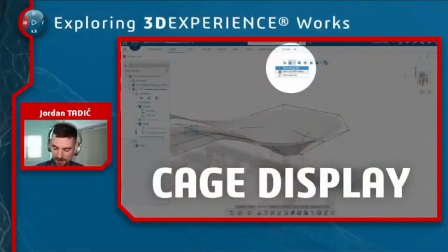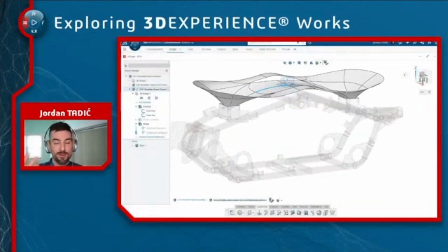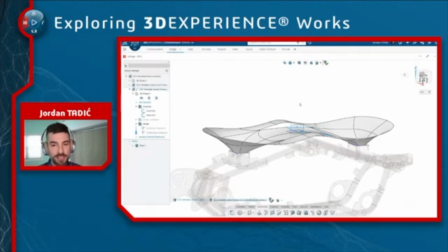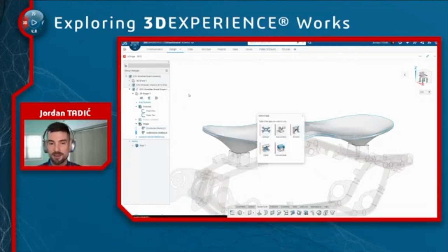But if I were to crease this edge coming in the Z direction, it would suck those edges right to the cage extents, and that would give us a rectangular shape. So, kind of geeky background information there, but that really is what makes you truly understand what's happening in the subdivisional environment so that you can get really predictable results and play it to your advantage.